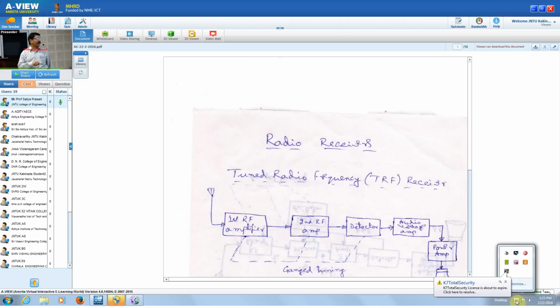And we have the detector, an AM detector or a phase discriminator for FM modulation. The output of this detector is audio frequency, therefore we provide voltage and power amplification of these audio frequencies. The output of this power amplifier is given to a loudspeaker to give our required signal in audio form, converting the electrical signal into a sound signal.